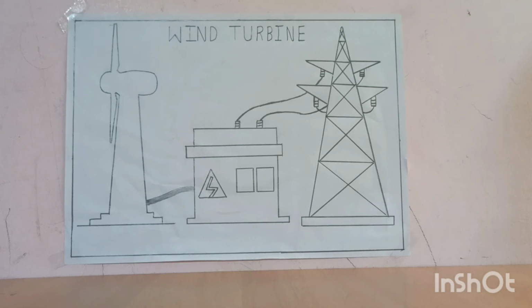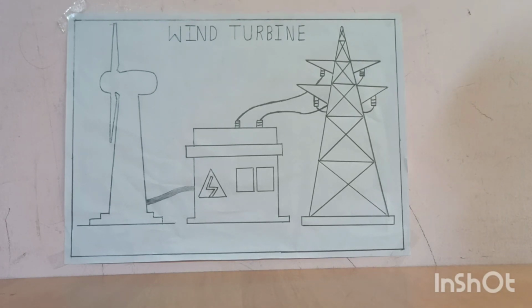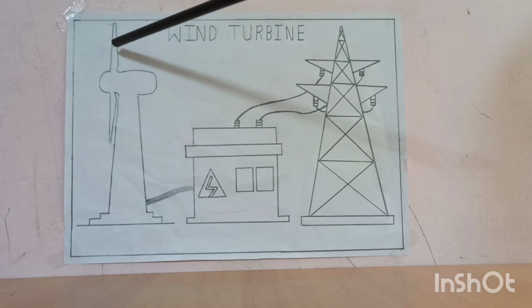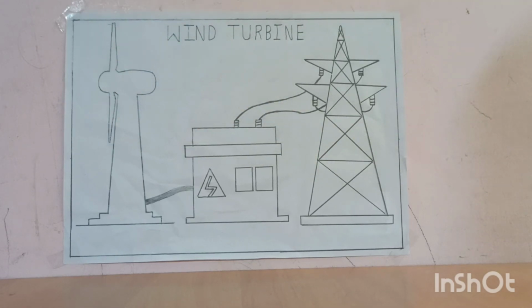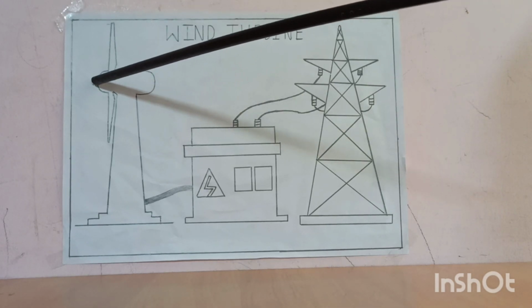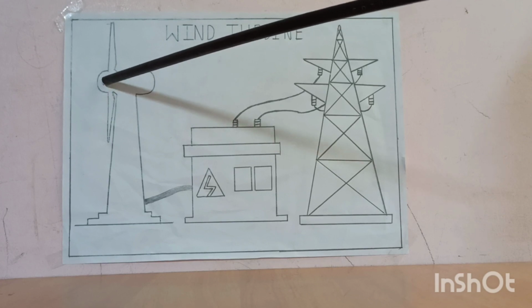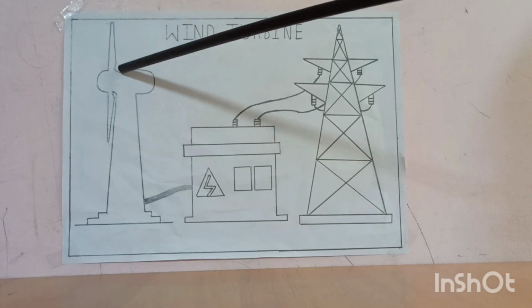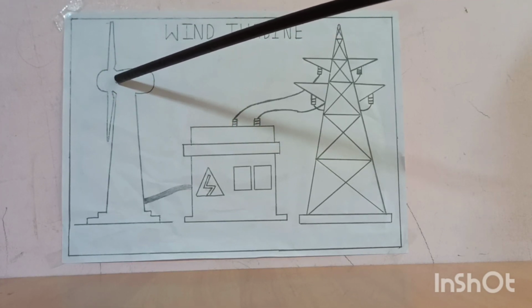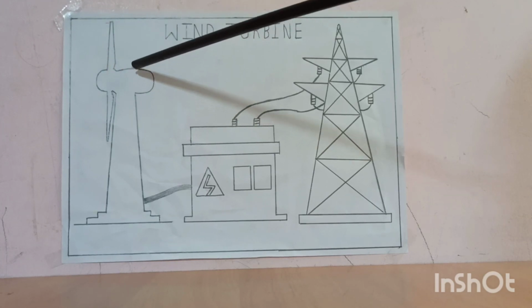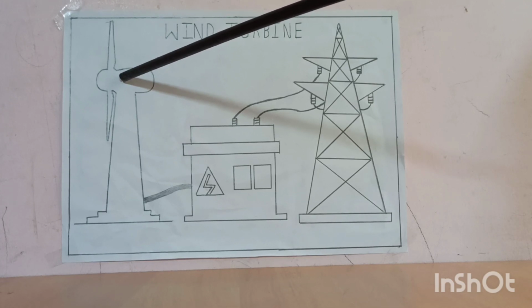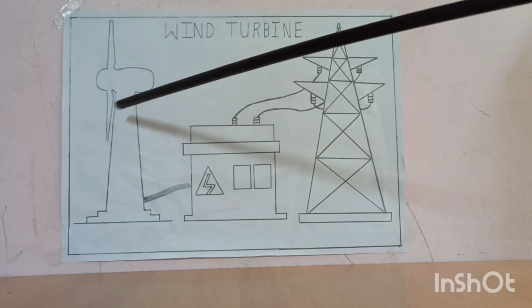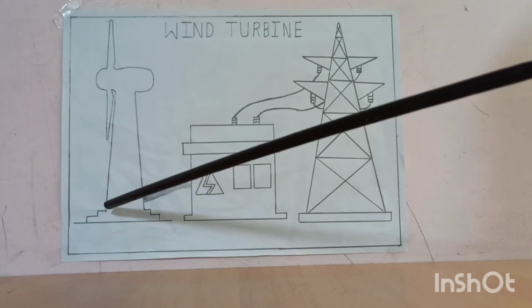Let's discuss the parts of a wind turbine. First, the blades. Here you can see it comprises three blades which are 120 degrees apart from each other. This portion is the hub, and this is the generator, which is applicable in onshore and offshore technology, and the gearbox, which is dedicated to onshore most of the time, and this is the nacelle. This is the tower, this is the tower foundation,